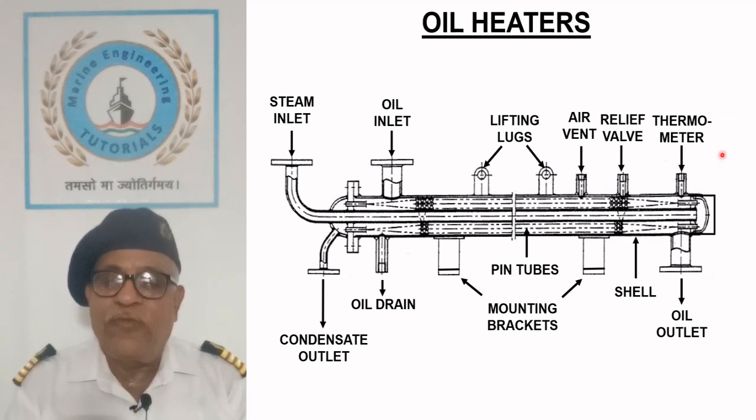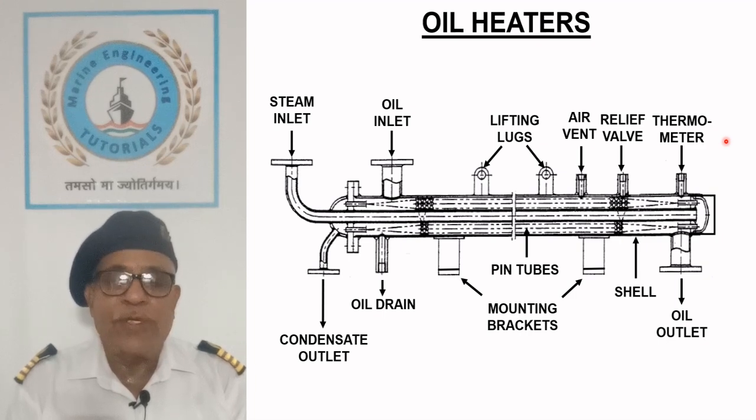Similarly, the shell is equipped with a thermometer at the oil outlet end for measuring the temperature. In addition, a temperature sensor may be fitted for automatic temperature control in case of fuel and lubricating oil heaters, for purifiers and auxiliary boilers, fuel oil heater. Diesel engines are usually equipped with viscosity controller instead of temperature controller.